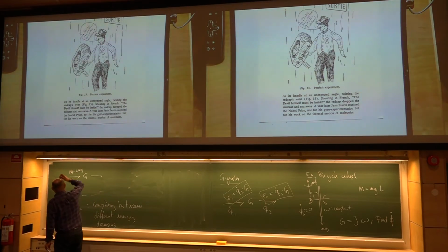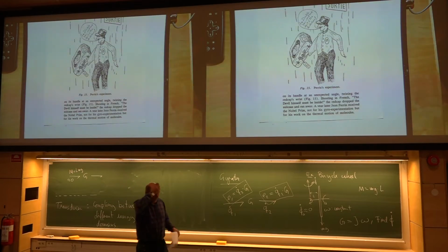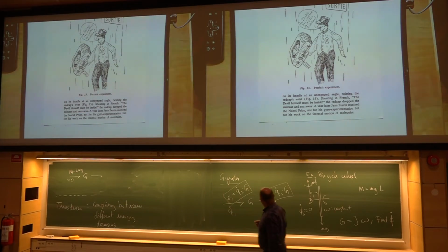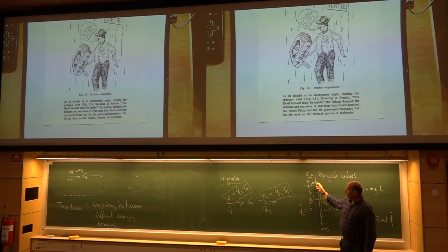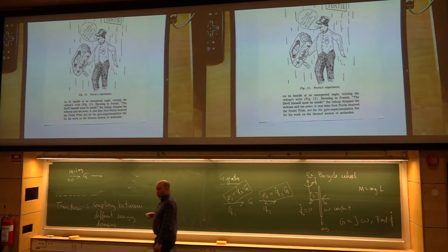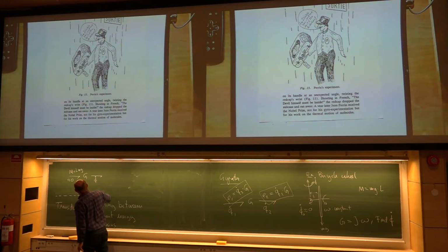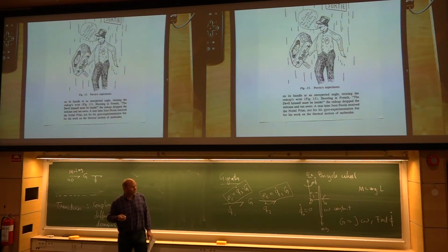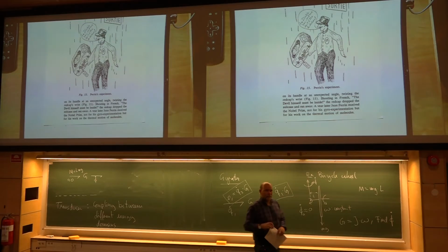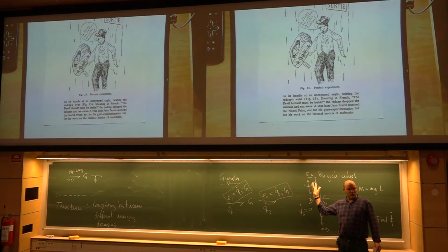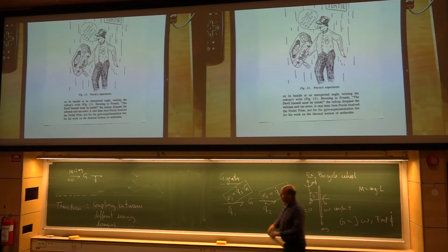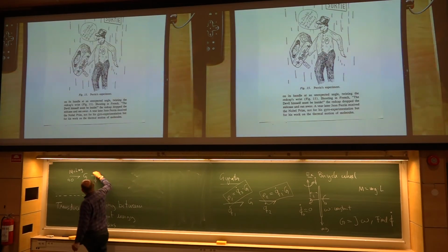What do I get on the other side? Well, I get this rotational speed around this axis. I get a phi dot here. That's the one I want to find. What about the effort up here? Well, I don't have any effort. Strangely enough, when you do the experiment, this rotational velocity is going to be constant. Meaning you don't have any torque acting in this direction at all. So the torque here is roughly 0.